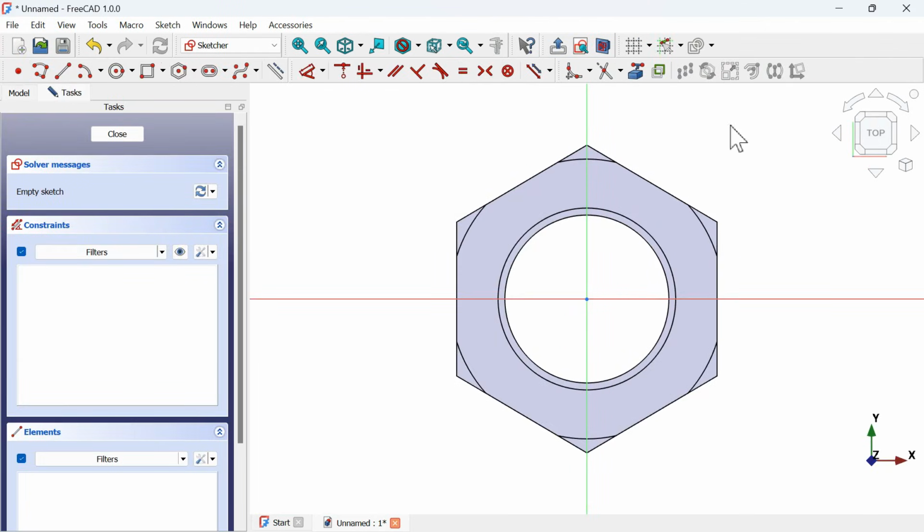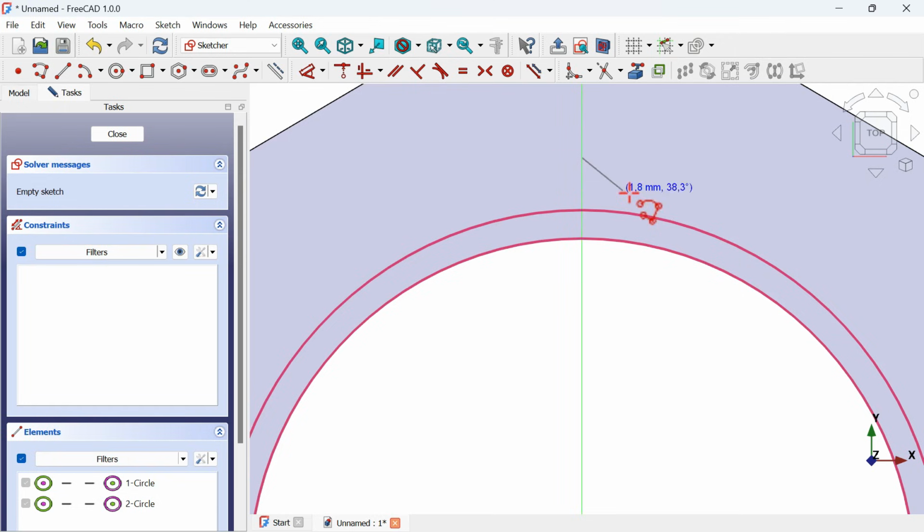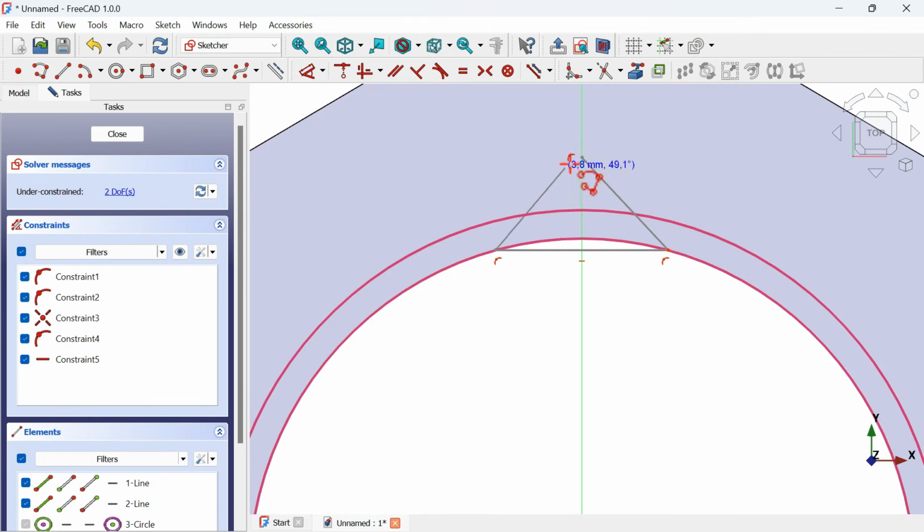And next, what you do, go to these tools here, click on the external geometry tool and extract this edge and this circular edge here, and now zoom in. Select the polyline tool, and now what you do here, just create this geometry starting from the vertical axis, and now click here on the circle and here, and now close this geometry in this way.